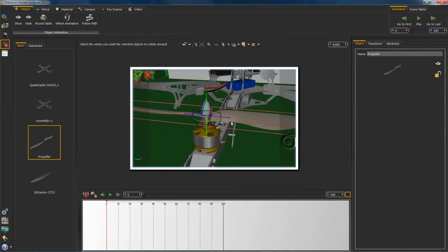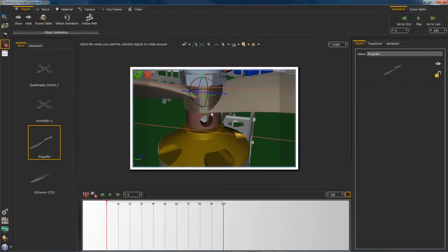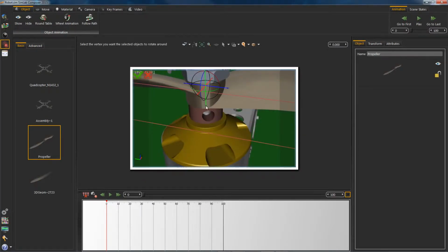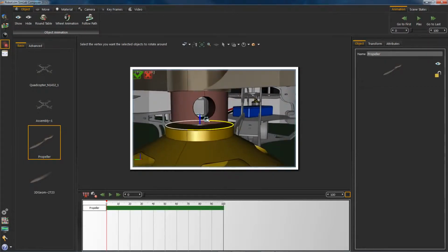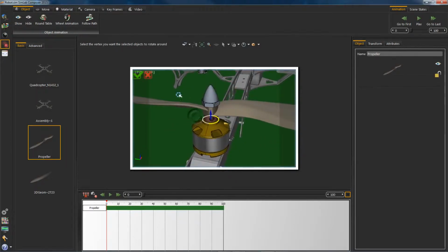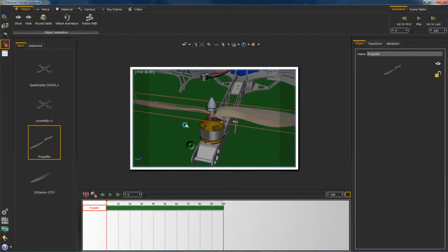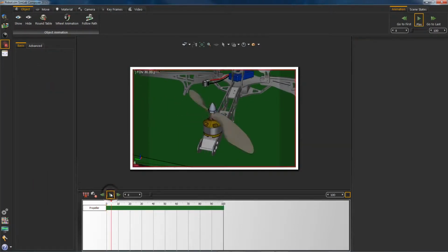Click on Pick Center to select the revolution axis. To do that, we must choose the curve. So head to the Common toolbar and select Pick Center of Curvature. This curve looks good. Always pay attention to the direction of the blue arrow. In this one it's normal and will go counterclockwise. Let's give it a test. Looks pretty good.